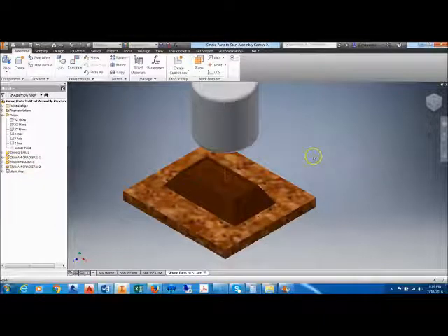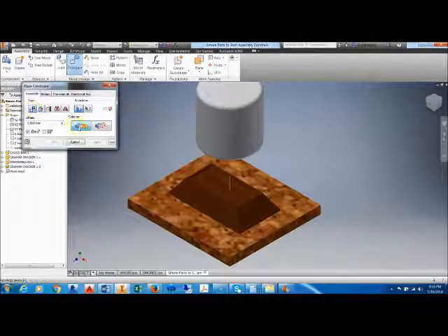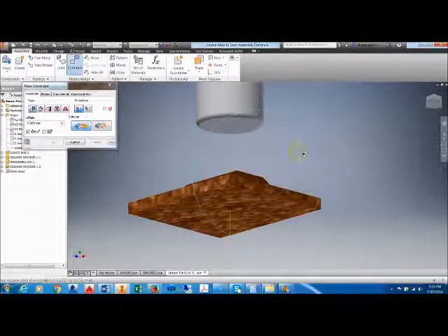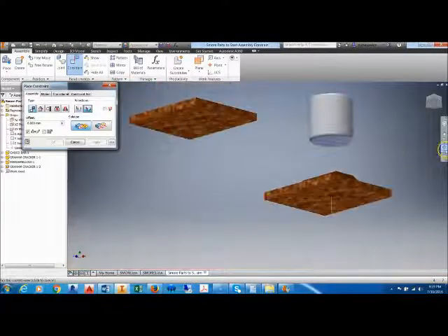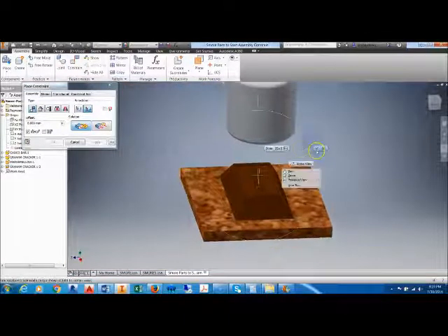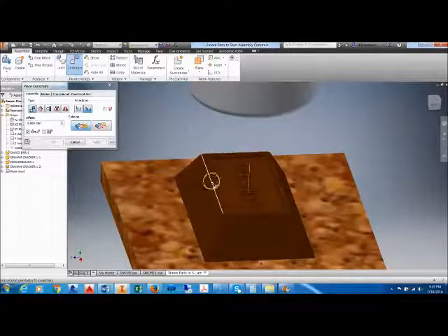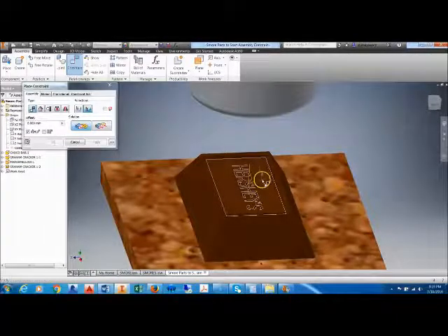Setting the height will happen in the same way, where we will grab the constraint tool again, and again it's going to be type mate, solution mate, and I'm going to then use my free orbit and rotate my entire assembly around so I can grab the bottom of the marshmallow, and it's the face of the marshmallow, and then I'm going to free orbit rotate back around till I can see the top of the chocolate. Now I can select the indentation face, or I can select the top edge of one of the pieces of edges of chocolate. I'm going to utilize the indentation face.